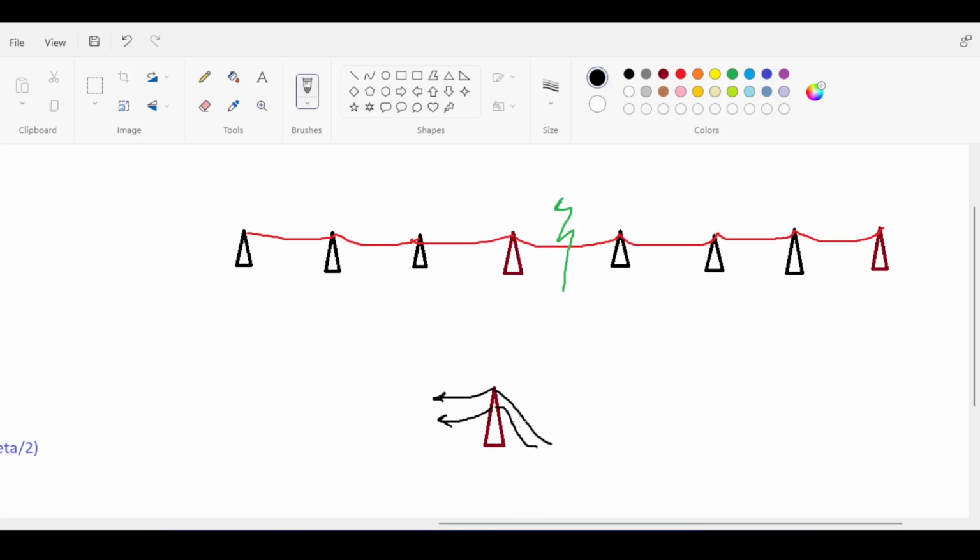So you have all kinds of problems here because suddenly, if those are cut, you have the tension on the other side. Now, this is a problem because suddenly the tower is under loads that you have not accounted for if you don't know this failure containment load. So if you don't design the tower for those loads, you will have extra loads that cause bending and all kinds of problems that could make this tower fail. Now, if this tower fails, then the same thing happens to the other tower because the loads will propagate, and then this will fail, which will cause the next tower to fail. And you see a lot of those hurricane aftermath pictures where you see a lot of towers leaning on their side.